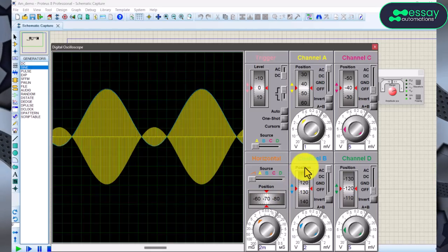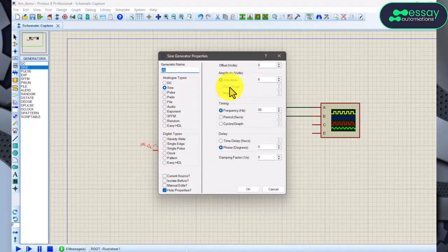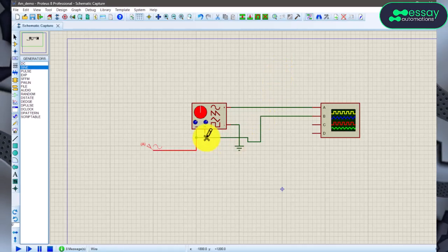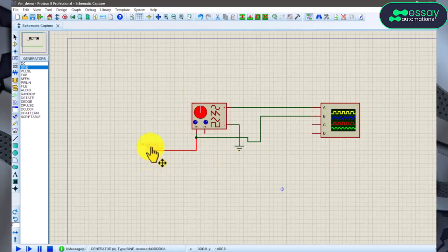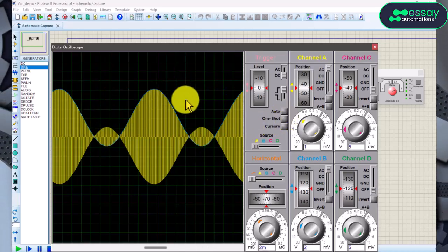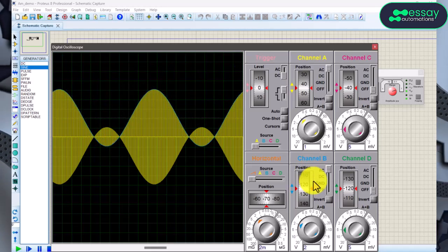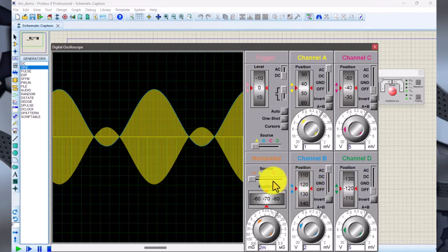perform simple amplitude modulation. So I hope you try different modulation amplitudes to get different modulation indexes. You can also change the frequency, and later, maybe in our next video, we'll try and continue this using an actual audio file. For this example, we are using a sinusoidal wave, so we see the edges follow the pattern of the sinusoidal wave, but we'll try it with an audio file and see how irregular the edges will be according to the amplitude of the audio file.